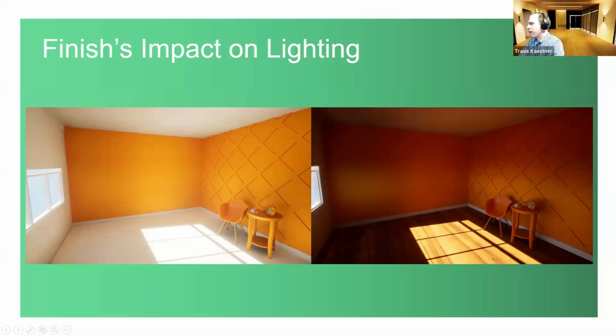Finishes impact on lighting. A lot of times I do a lot of calcs, and then I send it off, and then after that, it's just change. You don't always stay up to date. You can see this is just sunlight. This is the same time of day, but a white floor, and how bright that room is versus when you put in a dark walnut floor, and then all of a sudden that light, even from the daylight, all gets eaten up, and that room feels very dark.